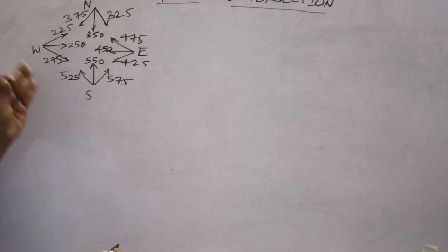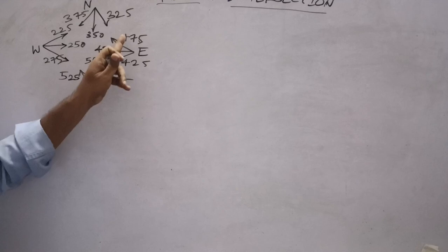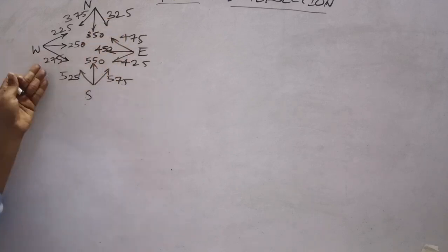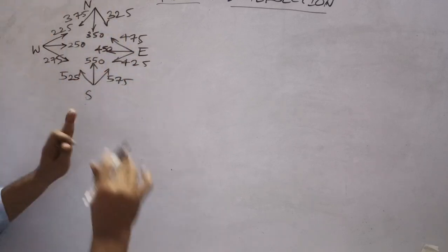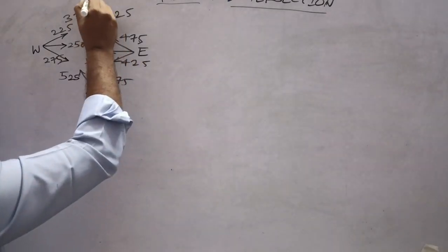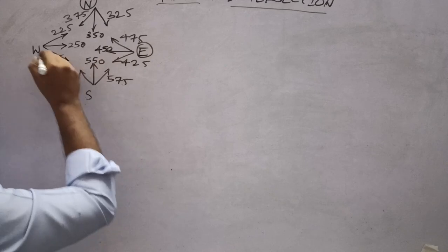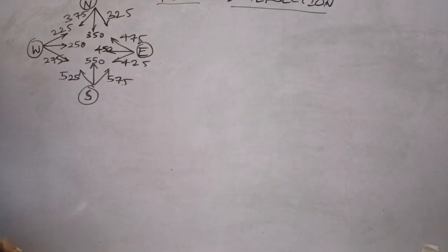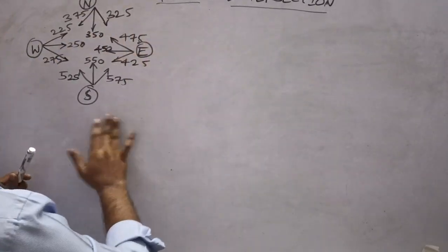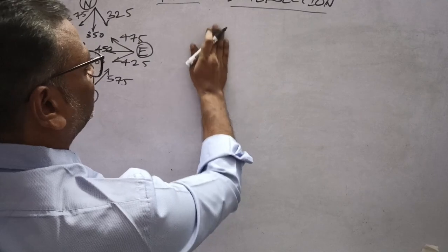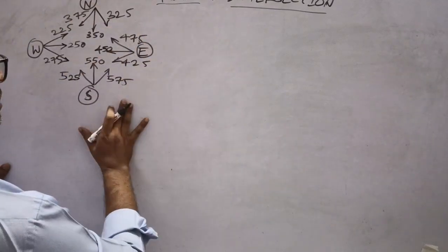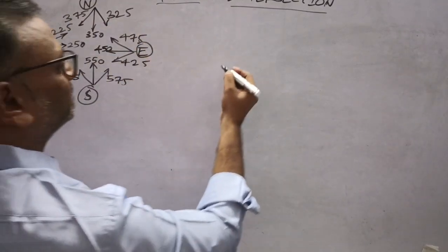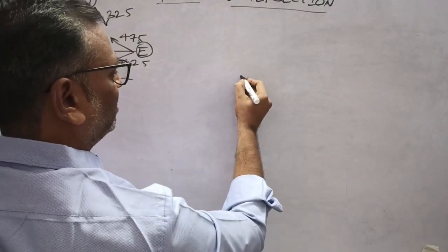See, all the left turning traffics I have taken 25s, right traffics I have taken 75s, for simplicity only. So we have north, east and west, south approaches. How to calculate capacity for this particular rotary, for this data we will see. So first take a rhombus.